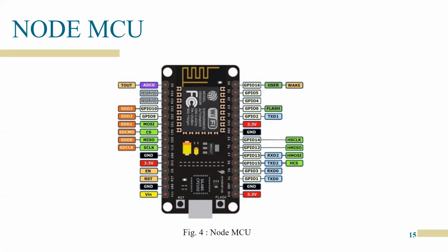And so as you can see, in Node MCU, there are 9 digital pins and one analog pin. As you can see on the left side, D0 to D8 are the digital IO pins. You can use them as input or output. And we have A0, which is the analog input pin. Also, you can see other pins, like for the supply voltage. It operates on a voltage of 3.3 volts. You can see various ground pins and TX and RX pins for the communication parts and all.